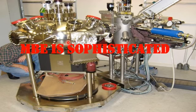Molecular beam epitaxy is also connected with multiple pockets, and these pockets are composed of a precursor material. So it's a multi-pocket setup. Apart from these, molecular beam epitaxy also consists of a reflection high energy electron diffraction setup, which is basically used to monitor the thickness of the film. So this is also another kind of device.